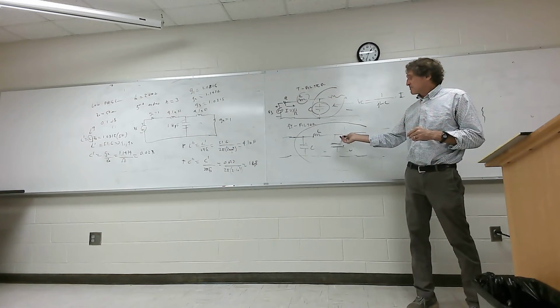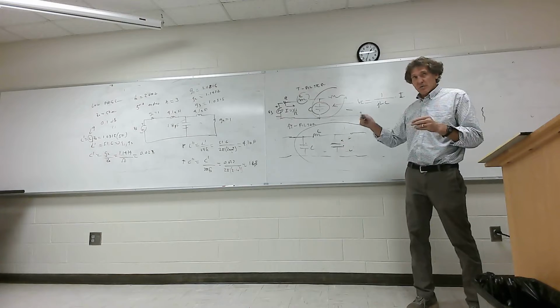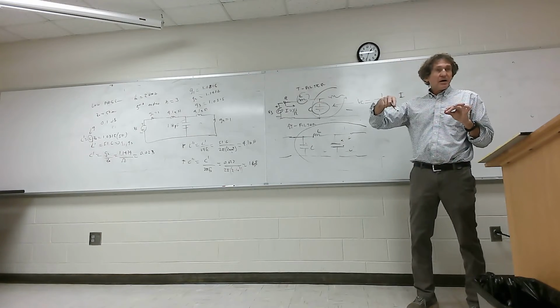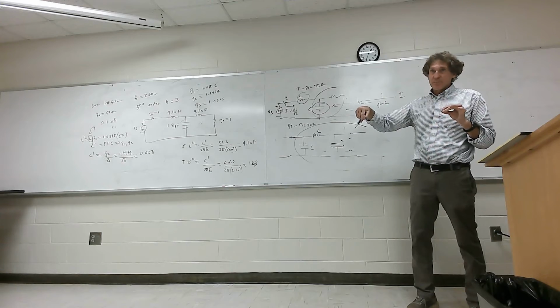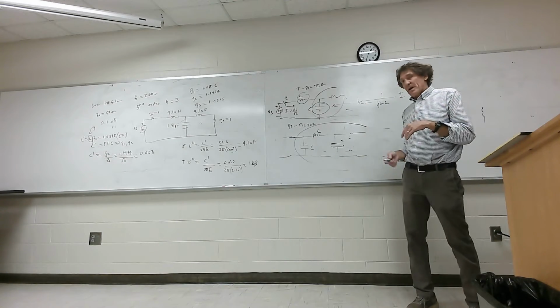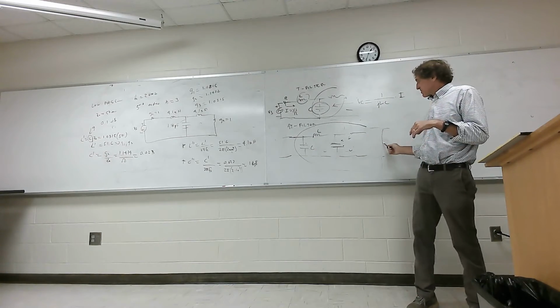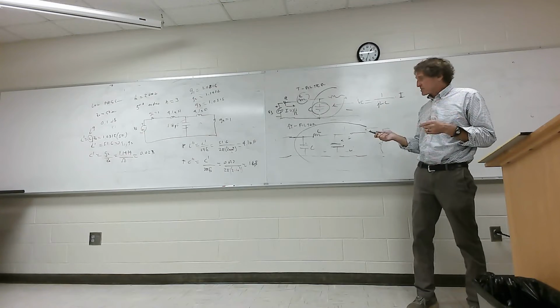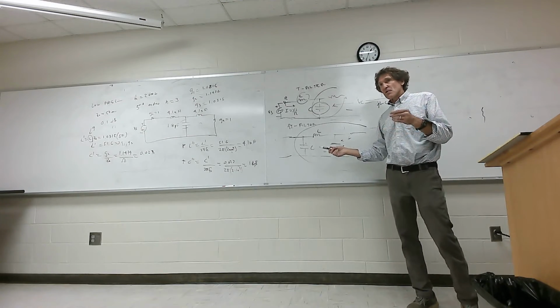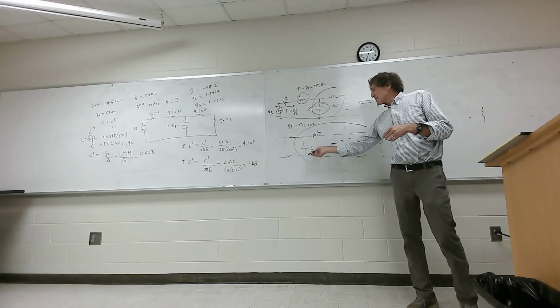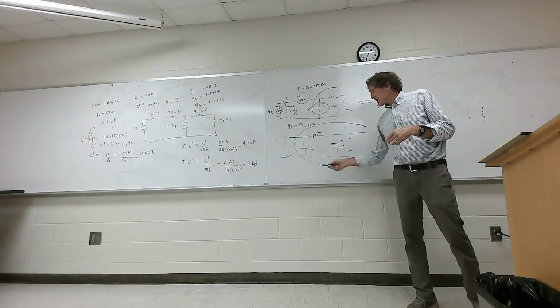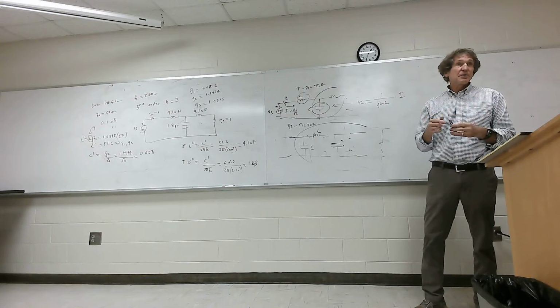So if you're ever building a power supply with a full wave rectifier, once you get a full wave rectified signal, you've got to get rid of that huge ripple. The way to do it is to put a capacitor there. Remember, it's going to discharge into the load, so the capacitor is going to charge up. But then you need to slow down the ripple directly from here, so they put an inductor in series and have a capacitor there. That's usually the way it's done.